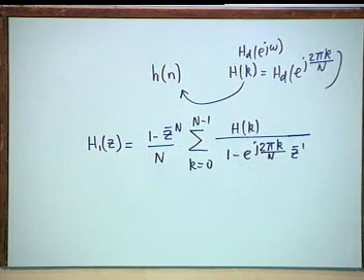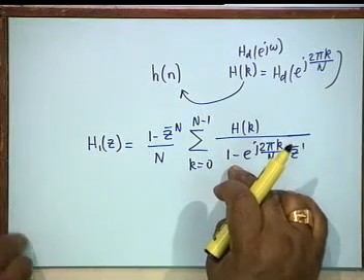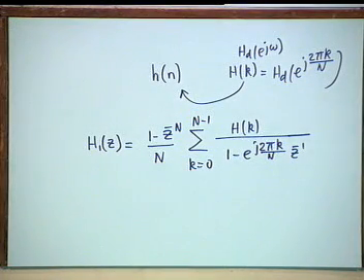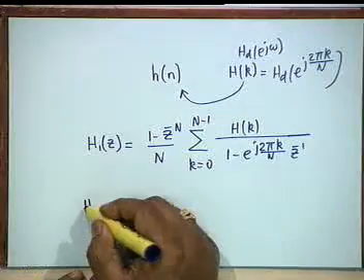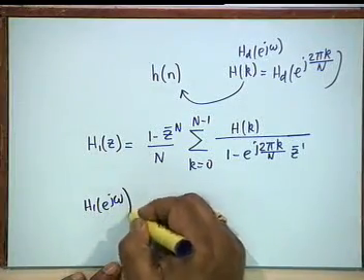And we are also tempted to interpret this as a parallel connection of first order blocks with, of course, complex coefficients, but then we desisted from that because poles are on the unit circle. Therefore, the utility of this expression is not in realization, but in finding the frequency response, that is H1 of e to the j omega.